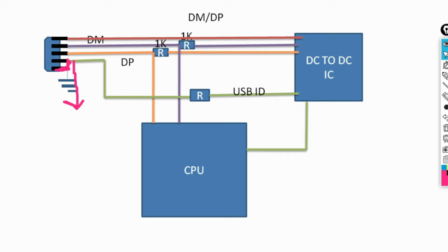Now what is logic high and logic low? I can explain everything in depth in the power section or other sections, but right now, this line is shorted, so the CPU enables the OTG mode. Now you can understand that your flash drive or pen drive needs some voltage to run. But when it is connected, VBUS is the charging line, DM and DP are for data transfer, and there is ground. So how does it work? Let's see.